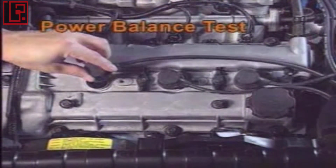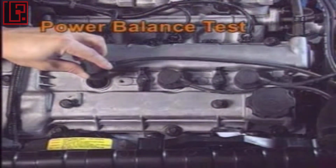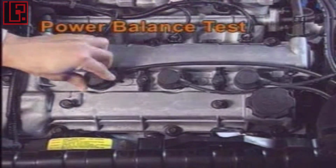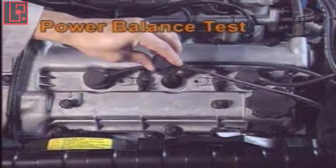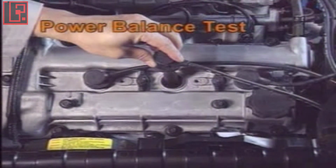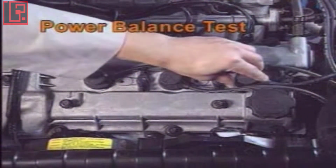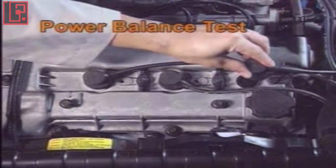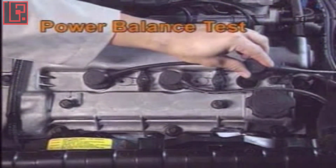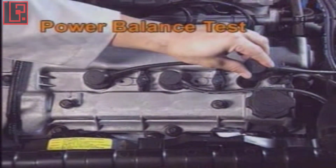For reference, when engine idle condition is not good, remove the high-tension cable from each cylinder one by one and perform a power balance test, which compares the engine condition. Through this test, we can find the trouble cylinder, and we can solve the problem by inspecting the fuel system, ignition system, and combustion chamber pressure, which may influence the combustion in the corresponding cylinder.